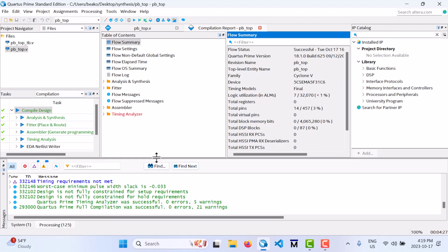So we will now walk through the process of uploading it to the DE1 SoC. To do this, first get your DE1 SoC out of the box. Then plug in the power cable. That is the big black block. Plug it into your DE1 SoC and switch it on with the red button. Then you will connect the white cable. It's really long. It has a USB-B at one end. Plug that in. You can refer to the handout for what I'm talking about.